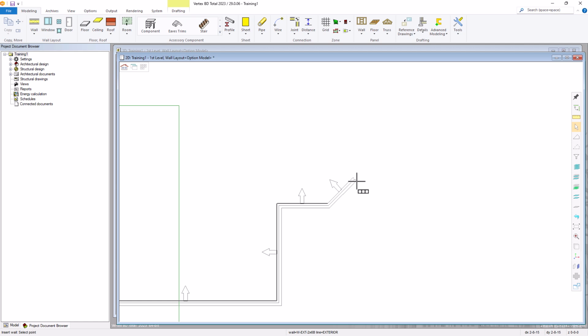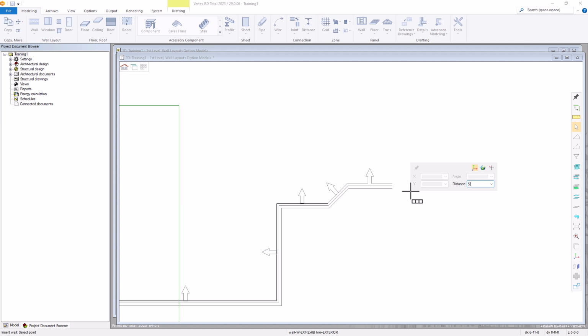Now let's say we want to add a segment at a 45. When we add a segment at a 45, using the 45-degree constraint, we need to know the length of that wall. So we're going to assume that it's 3 feet. We'll type in 3 feet. And because we are on the 45-degree constraint, it just wants to know the distance. So that segment is 3 feet long. And we can hit the U key, go over to the right, type in, let's say 5 feet. And now we use the 45-degree constraint again.